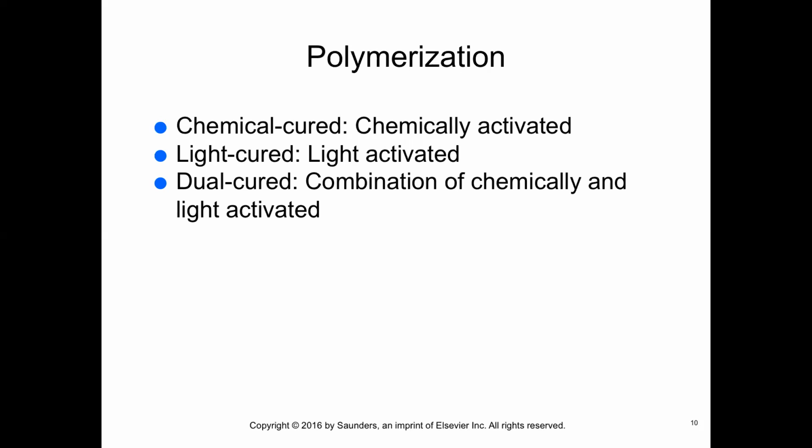The free radicals break on the carbon to carbon double bonds to form a single bond and another free radical. That free radical can cause the same reaction with another monomer to add to the polymer chain. When the branches of polymer chains share electrons, they form a covalent bond that links the chains together. Cross-linking the polymers produces a much stronger, stiffer material.